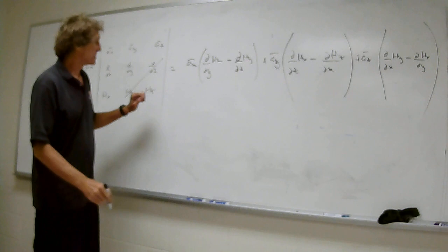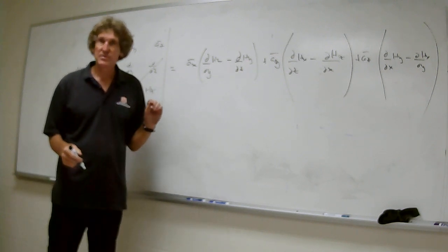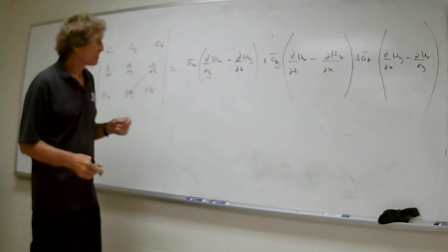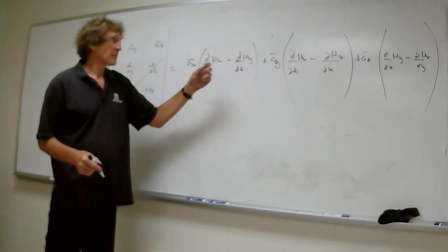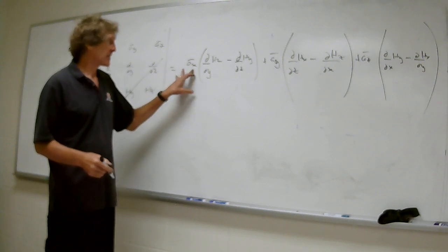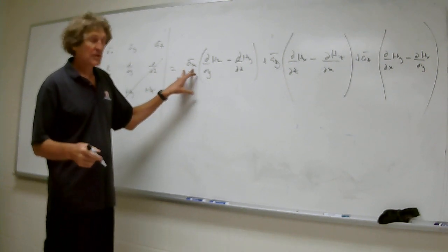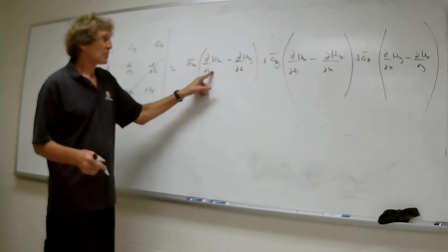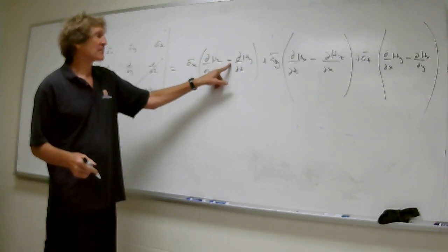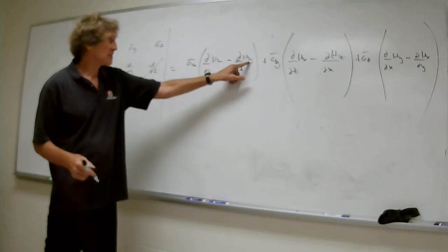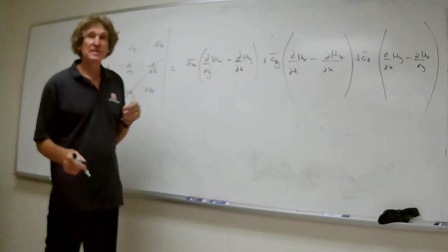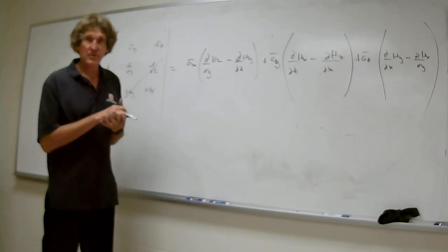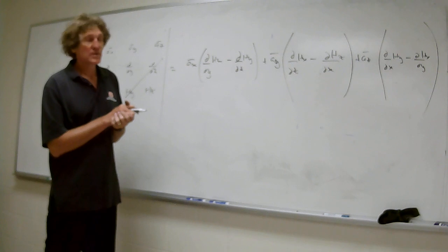This would be the curl of H in Cartesian coordinates. Once you establish what component you want, these derivatives and field values will not have that component. And if you take the first one, dHz/dy, you'll notice the next one is the same exact form, only you flip it. Now this becomes Hy, and this becomes d dz. In other words, there's a very predictable manner to doing the derivatives. So that would be the curl in Cartesian coordinates.